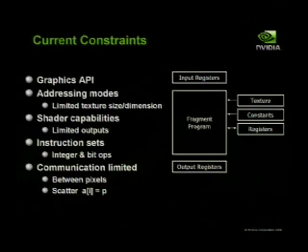If I had to explain this to a regular CPU guy, it would be defining your memory space as a segmented 2D memory space. And we've gone well past segments since, I think, 286 or something like that. The 386 got rid of segments. So it's very confusing. Plus, these images can only be of certain size, typically 4K by 4K elements. It's not a general purpose memory interface. It's a specialized memory interface. But for a lot of problems, you can get around that, but it's confusing.